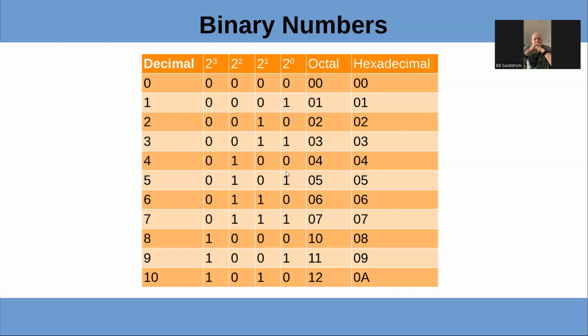And then we do a 1, 1, and then both of those go to 0 and 1. Well, we have multiple bit changes. Gray code reorients these patterns. So from one state to the next, there's only a single bit change, which helps in some communications and decoding. Weak signals, weak signals, that's where it is.